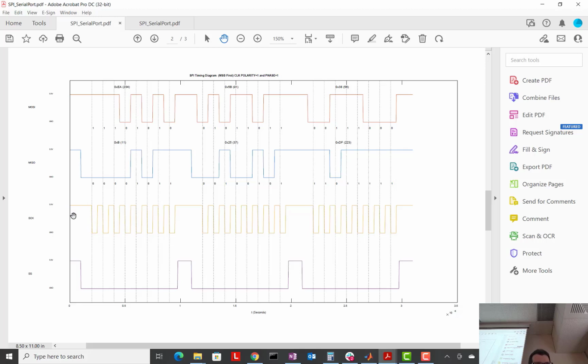And also, whenever it sees the chip select, it knows to set the pin to the most significant bit right away on chip select. Does that kind of make sense? Okay? And so it starts out at 0 because that's the most significant bit. It's a 0.